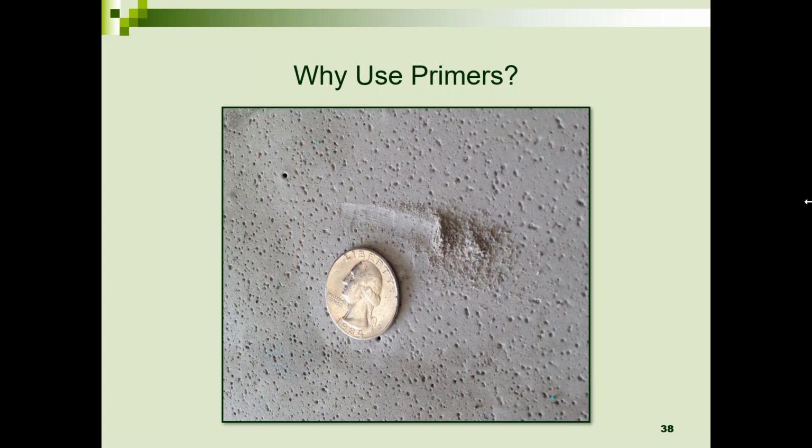And since the slab or substrate was sucking moisture out of the underlayment, you've got a weakened underlayment. That's shown here by taking that quarter and scraping and dusting the surface. If that underlayment was properly hydrated without losing moisture soon after application, you would not be able to scratch it as easily as we see here.